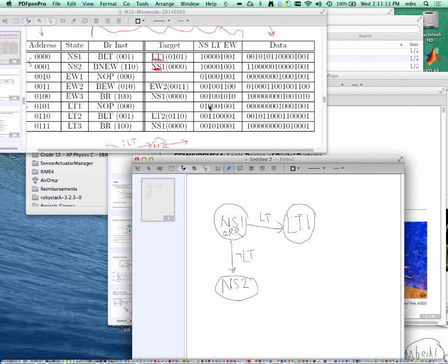You see it's 010, 001, 001. So before turning the left turn green, we are going to make the north-south direction yellow. That's what's happening here. You would see how the micro instruction, which is the data part of the ROM, consists of the branch instruction, which is 001. That's the first 3 bits.